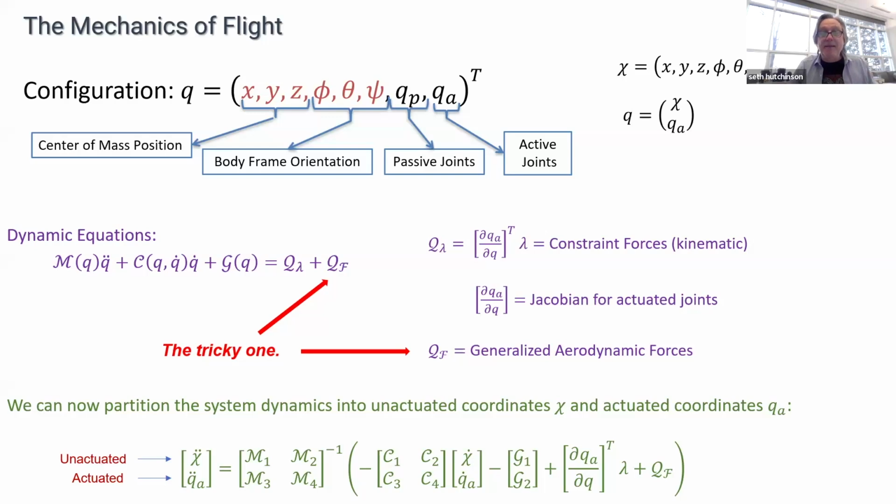And the thing that jumps out at you as being super nice is that everything on the right-hand side is independent of everything on the left-hand side. At the moment you add aerodynamics, that's no longer true because the aerodynamic forces depend on things like the wing speed. So the configuration variables and the state variables are directly related to what's happening with the aerodynamic forces. And so you can't do the usual kind of nice decoupling inverse dynamic control, for example, that you might do for a purely mechanical system.